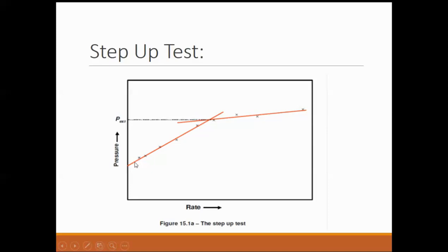If Young's modulus and all the other parameters match, then you can say this is a correct match, and this is the correct simulation of a frac job for that particular formation. This pressure matching is done after each and every job.